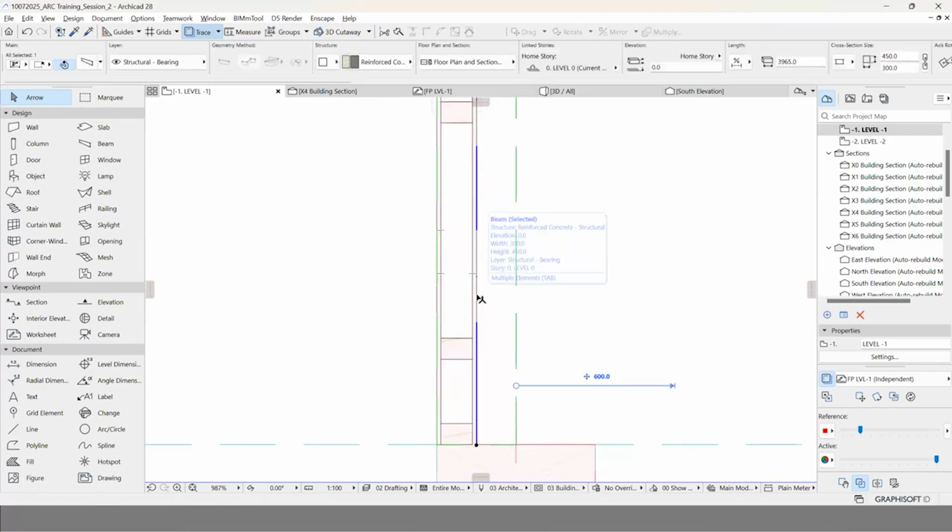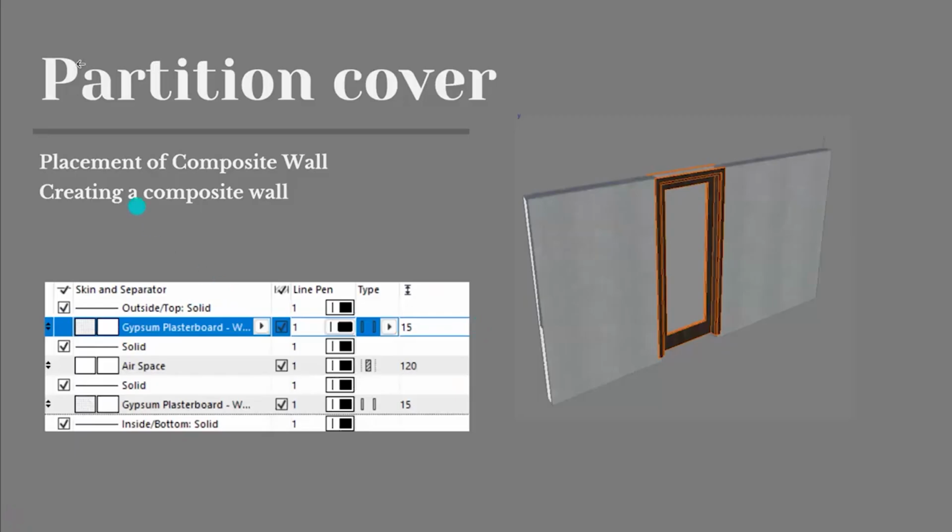So what I can do is create something called a composite. A composite is like layers of material. So you may have, just like what we want, a plaster layer, then for us it is going to be a cavity, but you can also give it something like a brick wall and then again a plaster. So this becomes three different layers. Instead of going for that basic one layer separately as two different elements, I could go for a composite where all three layers are together.